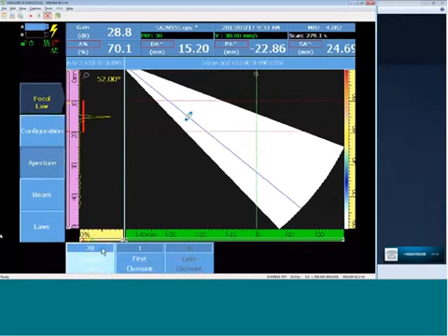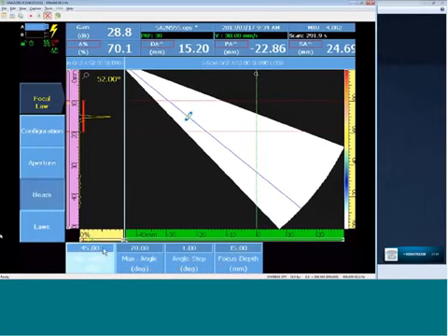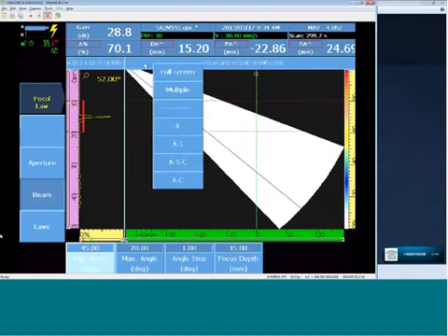So we've designed about a half an inch probe and a standard 45 to 70 degree sector scan at a 1 degree resolution. When we look at the S-scan, as I move it back and forth, we notice it is flat, the shape is normal, it looks good, it's at the correct depth. There hasn't been any calibrations performed yet, just a basic overview of the UT settings for the range and the filters.